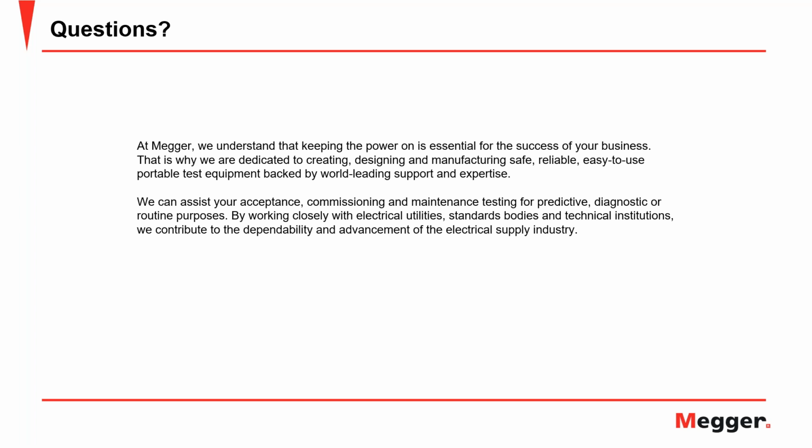Now, that can happen for a number of reasons, and the question is asking, is it going to be different for different types of transformer? Not only is it going to be different for different types of transformer, but also if two transformers were designed the same way, based upon how they are being used, what kind of loading has been put on the transformer, what kind of faults they have seen, the condition of oil inside the transformer, all those kinds of factors would impact your power factor measurement.